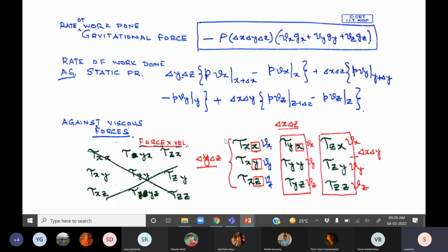So all forces which are related to work against viscosity are together called viscous dissipation. Viscous dissipation is due to the flow. Obviously, if the system that we are considering is a solid, or if there is no motion, then the viscous dissipation term would not be present.